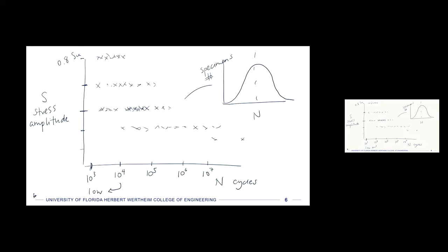All right, so we do something like that. That's how these SN curves are created. So if you look up an SN curve for a particular material that you are interested in, this is where those come from. So there is some scatter in just creating the curves in the first place. And this is good. This is where you would use this curve in an undergraduate class, and you would apply a bunch of factors to it. I'll just review those briefly so that we're all starting from the same place.